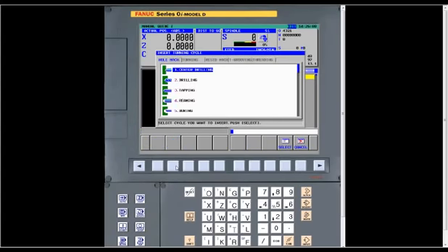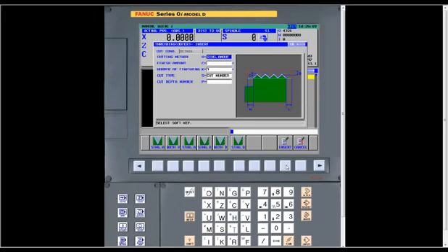And we go back, put down our grooving, now threading. Again, threading is very simple. Fill in the blanks again. We select threading, outer. The cutting method is just how it is feeding the tool into the thread itself. And it defaults to single amount. What that is, is like on an engine lathe when you've got your compound set up on 30 degrees, and as you go in deeper into the thread, it's only cutting on the leading edge of the insert. That's what it defaults to.